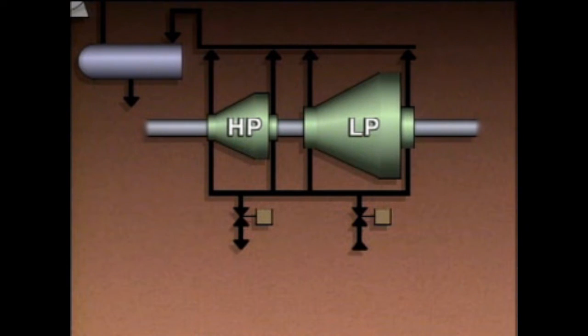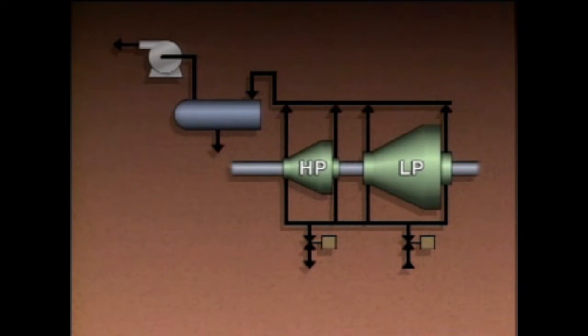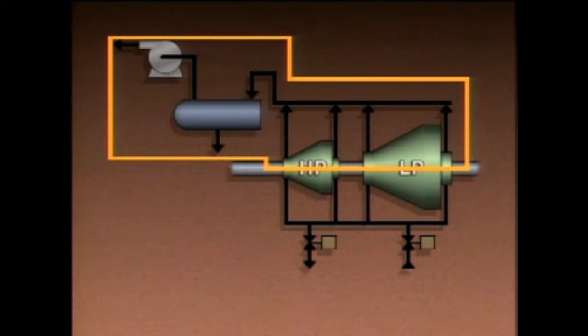If the pressure increases to a certain point, the steam leak-off valve opens to prevent pressure from getting too high. Steam that passes through the leak-off valve is directed to a low-pressure area such as the main condenser. Now let's turn our attention to the Gland steam seal exhaust system.